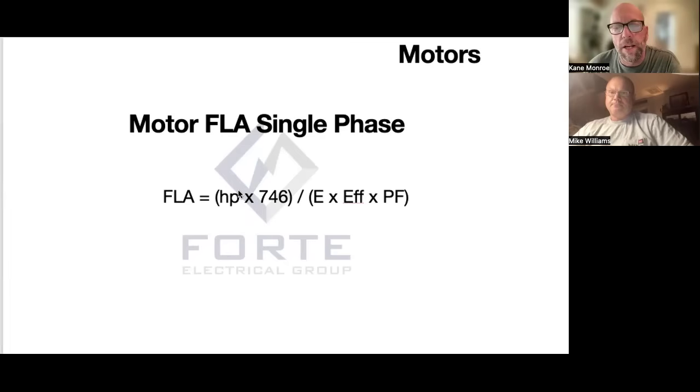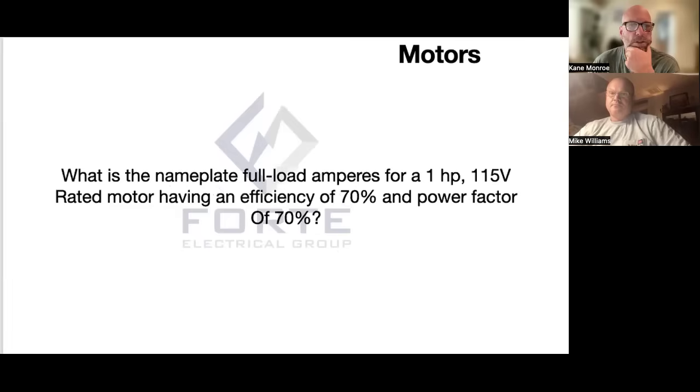So there again, say we don't have power factor or efficiency, but you know the wattage of the motor, you can take that, and if you know your horsepower, then you know your FLA. There are questions where you have to work just this section of the equation, 746 times your horsepower, and they want to know what your FLA is. Okay. So just wanted to get that introduced to you.